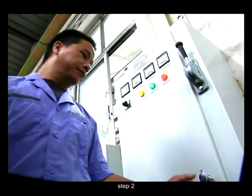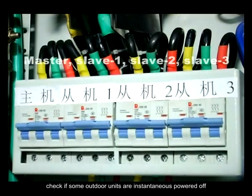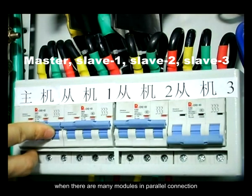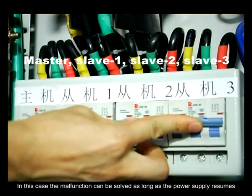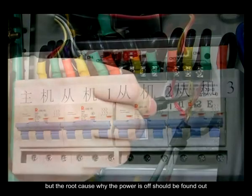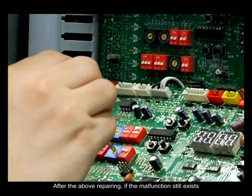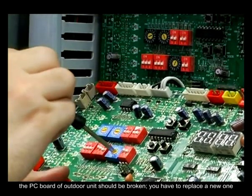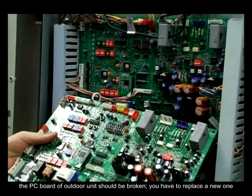Step 2. Check if some outdoor units are instantaneously powered off when there are many modules in parallel connection. In this case, the malfunction can be solved as long as the power supply resumes, but the root cause why the power is off should be found out. After the above repairing, if the malfunction still exists, the PC board of outdoor unit should be broken. You have to replace a new one.